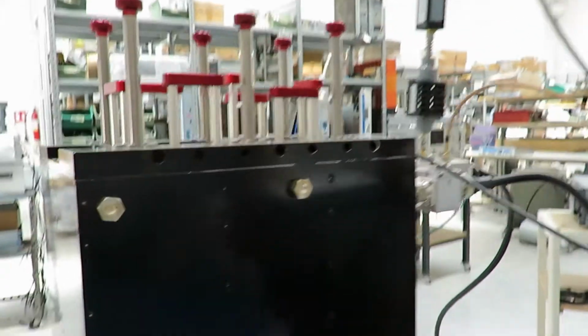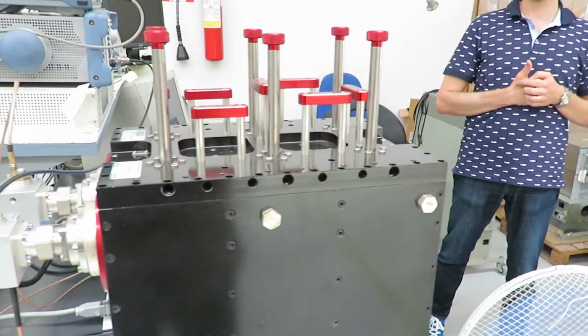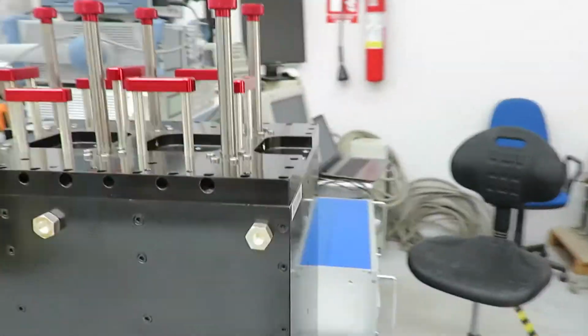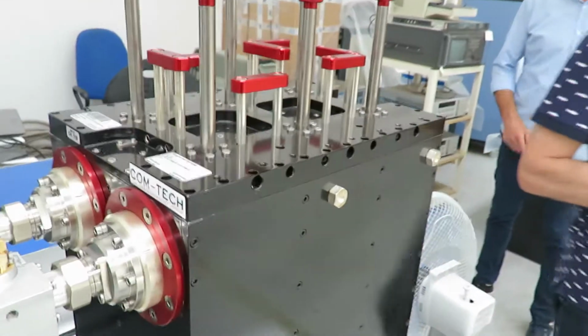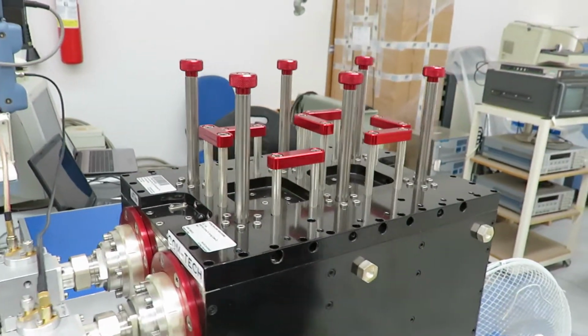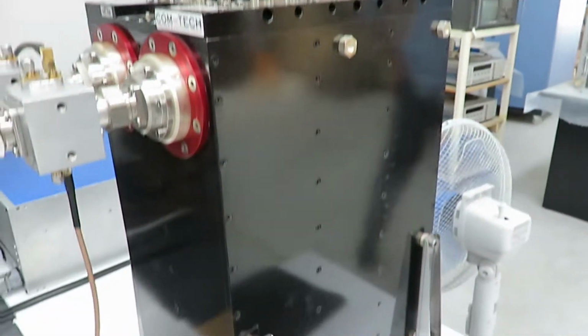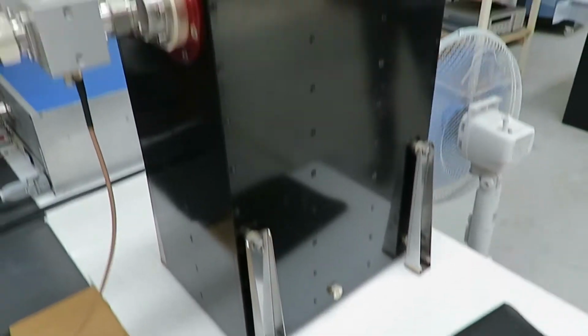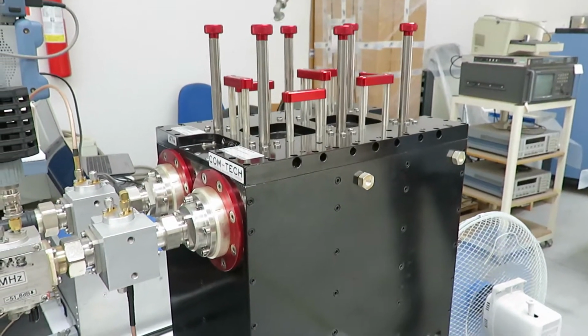Okay, so this is the cavity filter, which is produced by another company, from what I understand. Yes, a third party and partner of Neetra since a long time. It is 6 cavity, and it is the standard to allow rejection of out-of-band energy and to be compliant with the mask filter required by the ETSI official recommendation.